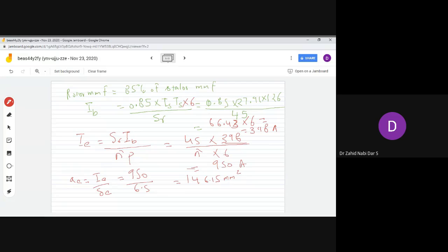So you convert to meters because the other value, 0.021, is in ohm per meter per millimeter square. So first of all you have to establish all the terms in the same unit.